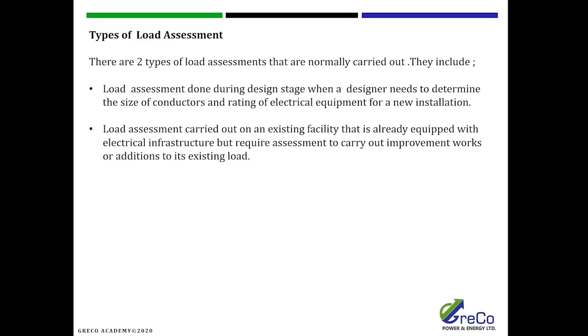There are two types of load assessments that will be carried out. One is load assessments done during design stages, when a designer needs to determine the size of the conductor and rating of electrical equipment for a new installation. The other type is usually carried out on an existing facility that is already equipped with electrical infrastructure, but it requires an assessment to carry out an improvement work. So either the designer is looking at load assessment from the design stage, or after the facility is already available and you're trying to work on improvement.